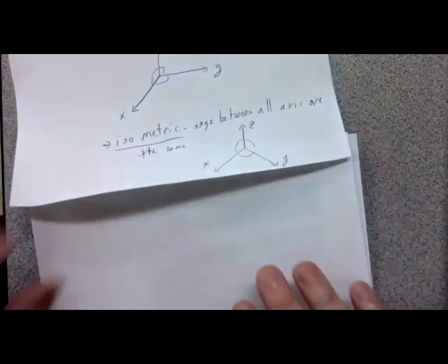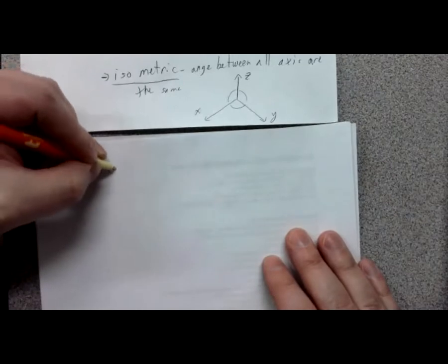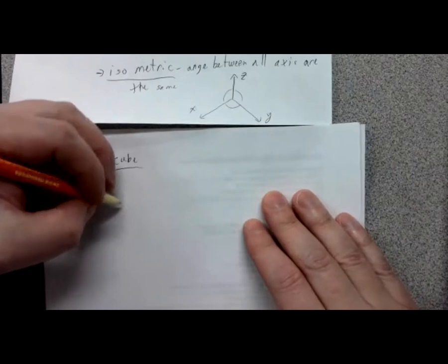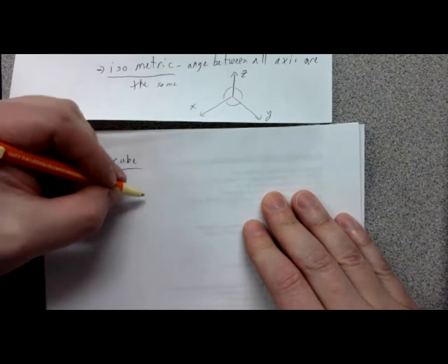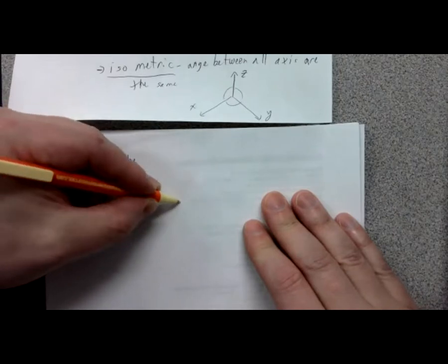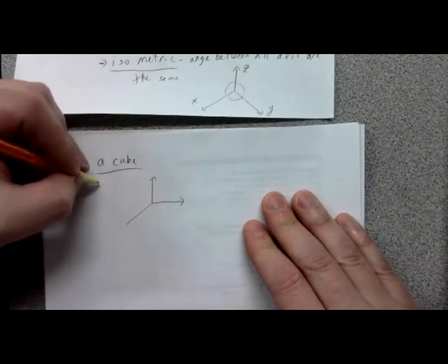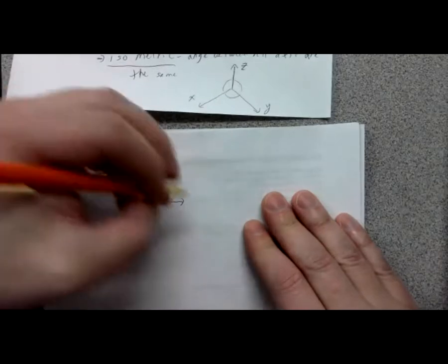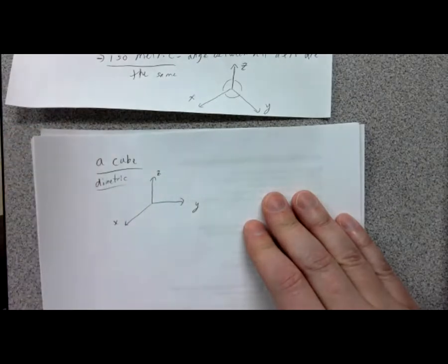So if we were to quickly draw a cube based on these configurations here: if I'm going to draw something freehand without a grid, I like to first draw what angles I'm going to use, what orientation. So if I draw a standard dimetric where I put Z vertical, Y left to right, I'm drawing X roughly off and down this direction over here.